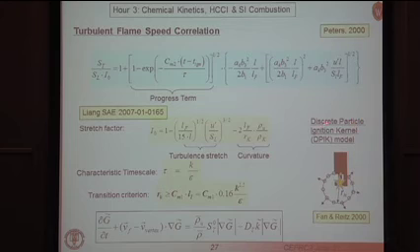So that's where our kernel model starts. We have ignition occurring. We have all these particles that represent the location of the flame. They move out at a velocity given by roughly the laminar flame speed. Then this term becomes bigger and bigger, and eventually we transfer to the turbulent flame velocity. So this transition between particles and the G model, which is shown again down here, occurs when the size of this kernel becomes comparable to the turbulence length scales in the engine.